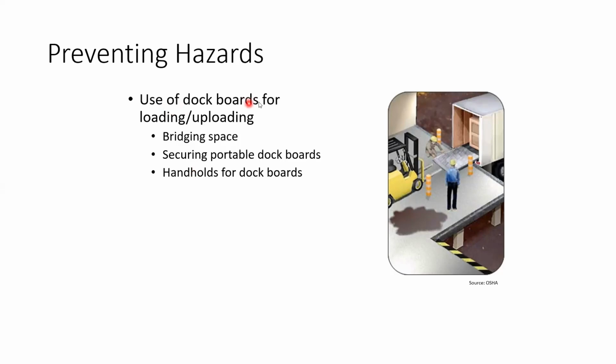Here, use dock boards for loading or unloading. Use an appropriate weight-rated platform to bridge the space, secure portable dock boards so that they will not move, and ensure that the dock boards have handholds or some other effective way to lift.